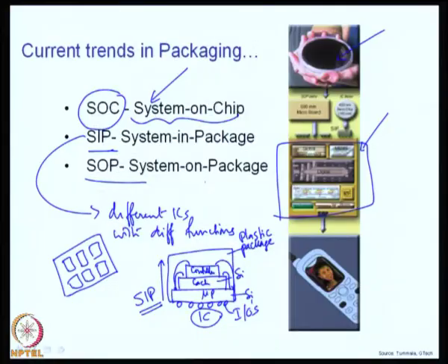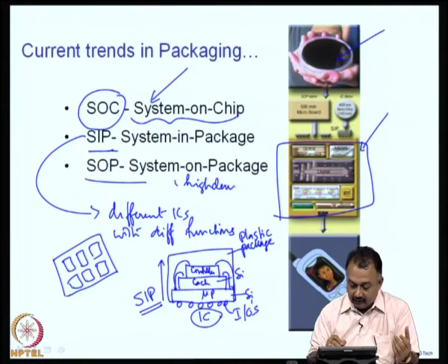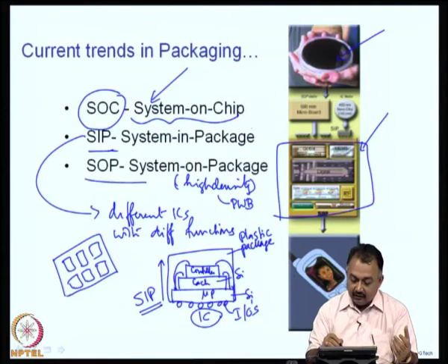You can have multi-layer interconnections using copper, and each of these layers can be connected by micro vias, very small via structures which connect the various conductors. You can embed passives into the layers of the substrate. So, this becomes a high density package, a high density interconnect system, and this is on a PWB typically, whereas here you can use ceramic or organic substrates.